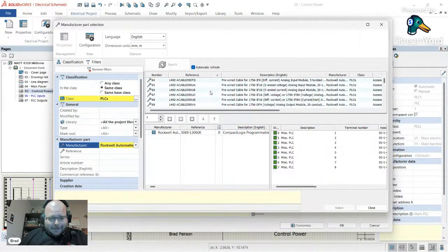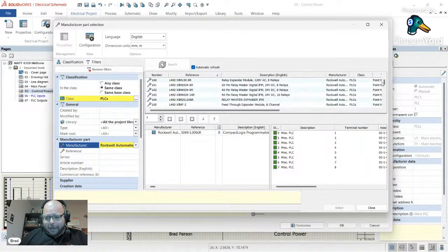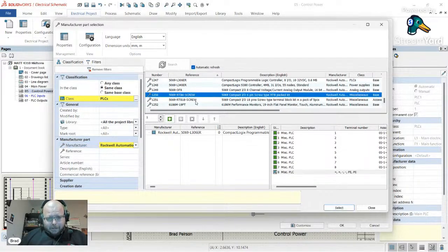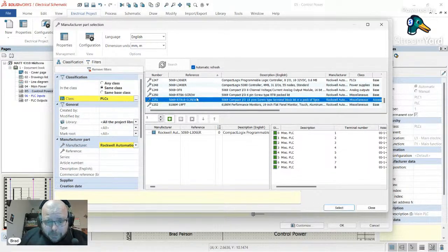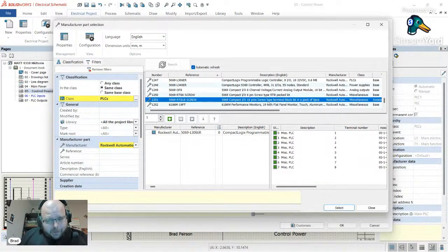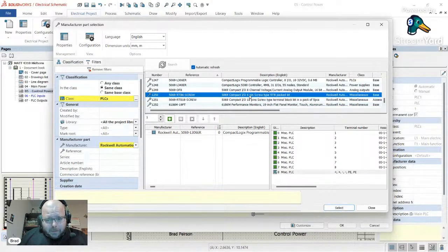Allen-Bradley does not include power terminals. You will order it and have nowhere to put wires. You need to separately order them. And I believe you need both of them. You need to order these with your IO. This is a 16 point or an 18 point pin. This is a 6 pin.